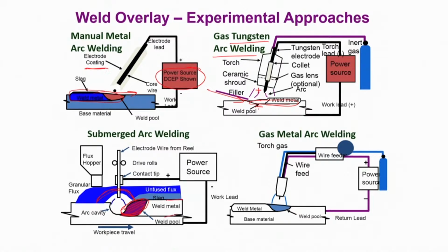So this is the region in which you have created the overlay by using an electrode to create the very high arcing, and along with that you have a mechanism of feeding the flux which covers everything, so the entire arcing and the entire fusion zone is in a submerged condition.